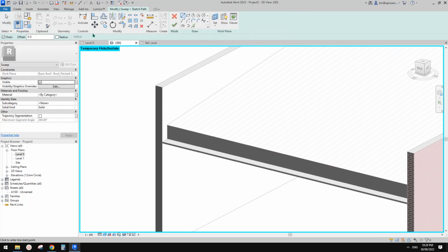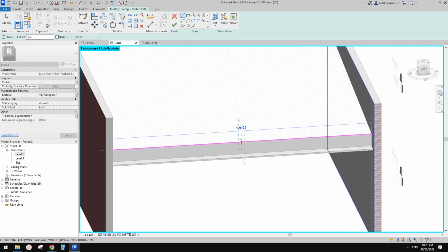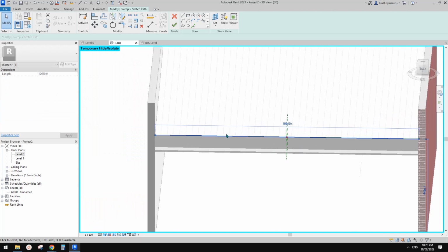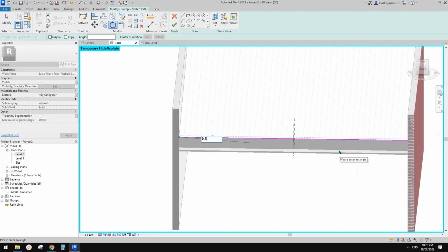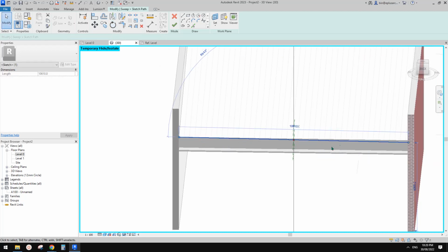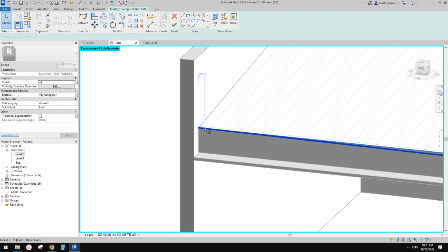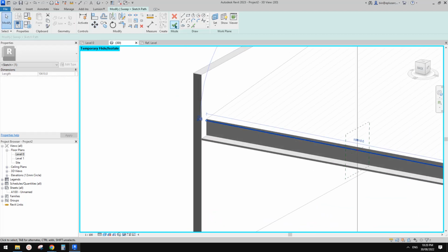Sketch path. Did I use sketch path? Yeah, good. Or sketch path, and then draw this line first. And if you want to set 1 to 100, you can RO space and rotate it by 0.57. So this is 1 to 100 slope, and then you can decide, okay, let's move it down by 50 or something like that. So just move it down and then finish.